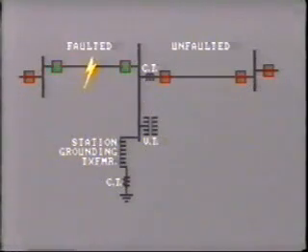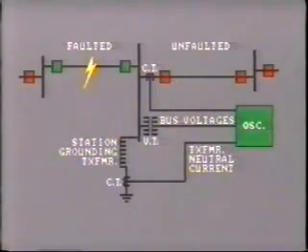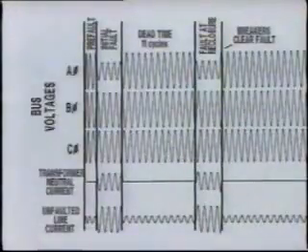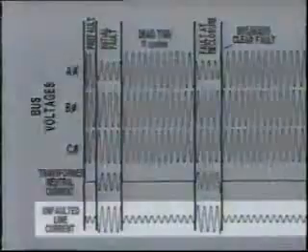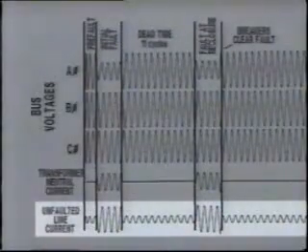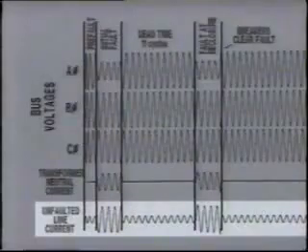In practice, this happens quite frequently when the line does not stay de-energized long enough for a temporary fault to clear on its own. In this example, the oscillograph has captured the substation bus voltages in all three phases, the transformer neutral current and line current for one of the transmission lines. The oscillograph system in use here can record 3 cycles of pre-fault data. From the trace of line current, you can see that the line we have monitored is not the faulted line. This is obvious since the current resumes its normal load level after the fault is cleared.